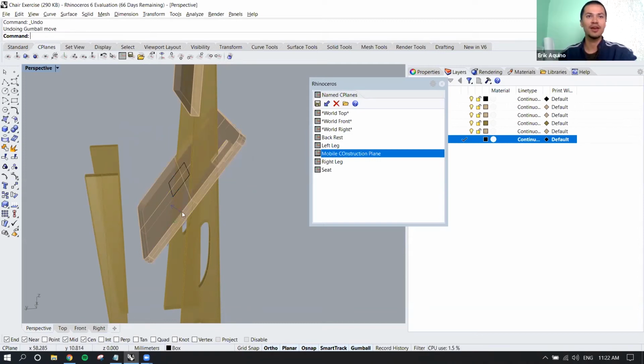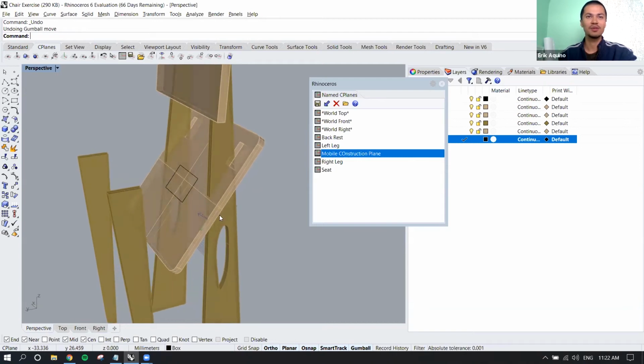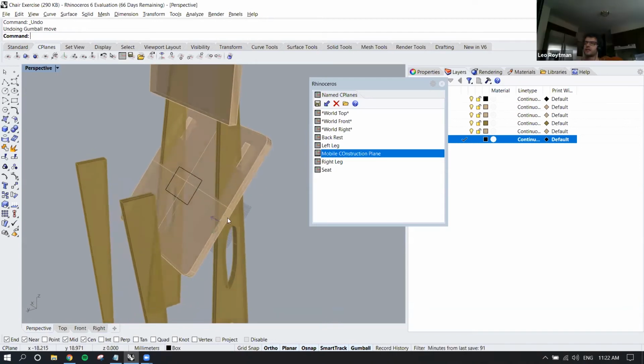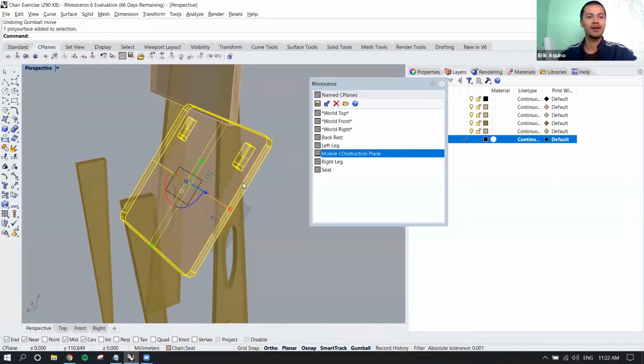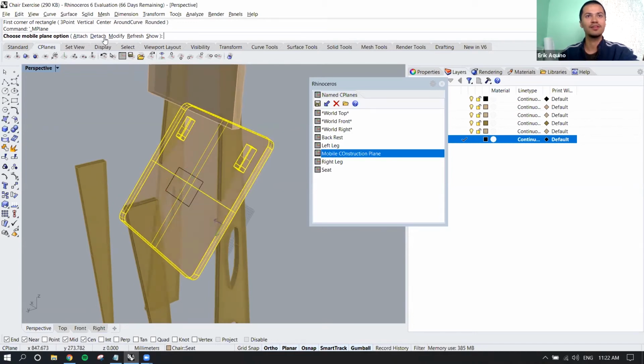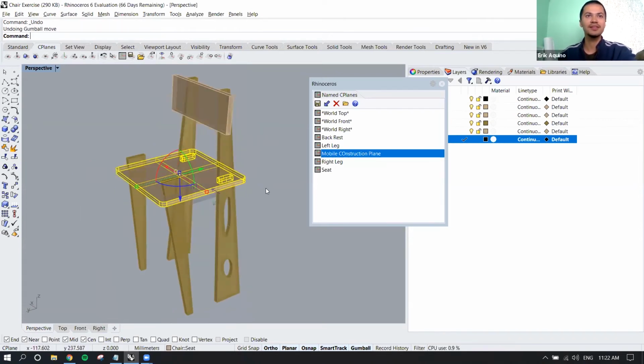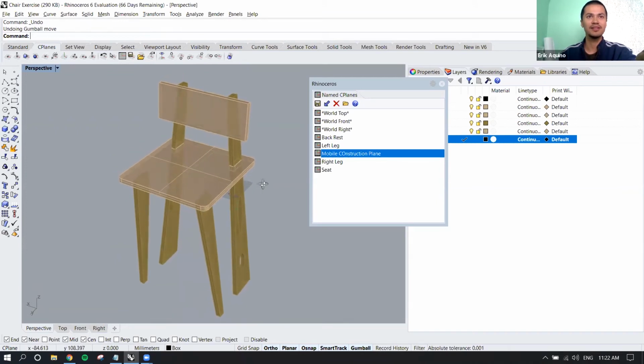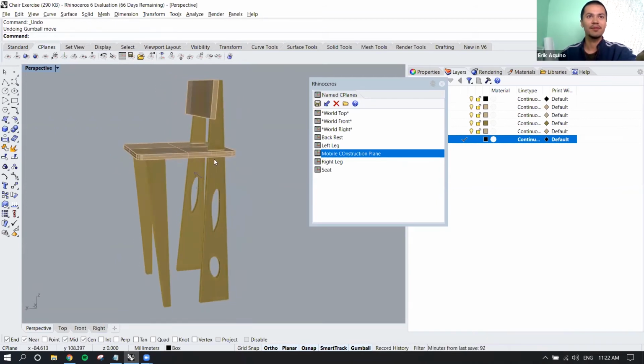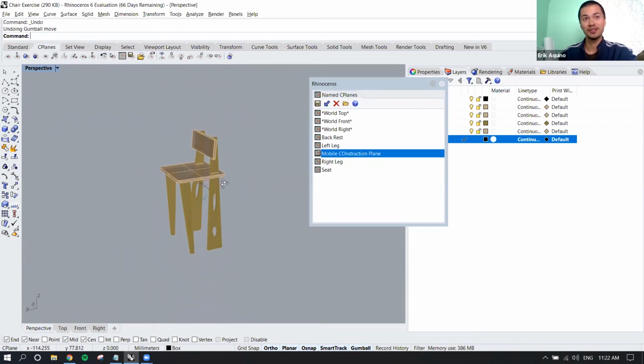You're saving the location of it and wherever position that it was placed. So basically, we cannot come back to a mobile construction plane. It will be mobile only while it is active. Yes, exactly. And then that's where you have the options to attach and detach. So it's always based off if it's on or off, basically. All right, so that's basically the gist of construction planes, and we'll now move on to an exploded isometric.